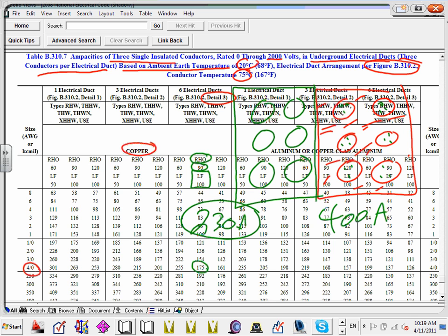And how are you going to size it? We're going to size it based on what conductor should be sized based on this, which you end up with a bigger conductor. What we did, guys, at Elevator Bucket, when we sized them, we always sized them based on a software that we had, Spencer, called AmpCalc, and it comes with the same calculation, by the way. But you can build these as 12 ducts encased in concrete, one system, 12 ducts. The code doesn't talk about this. There's nothing in the code about 12 ducts encased in concrete at the same time. So what do we do? We build them in a software called AmpCalc.